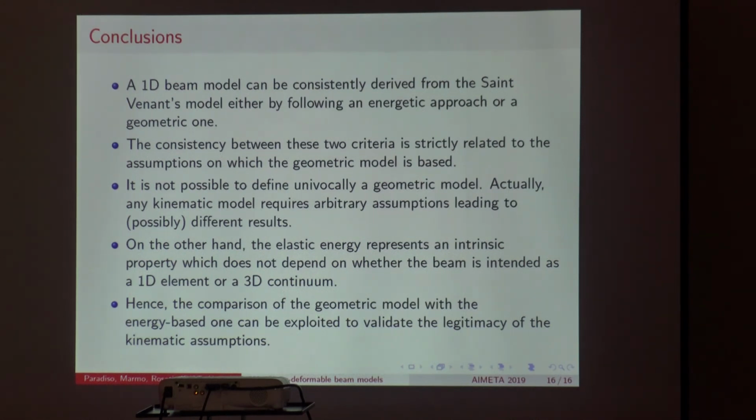But if you define the normal force as an integral applied at another point, you have a coupling between the normal force and the bending moment, the static moment. In this case, the coupling between shear and torsion could be seen as just a matter of constitutive representation. Do you agree with this point of view?